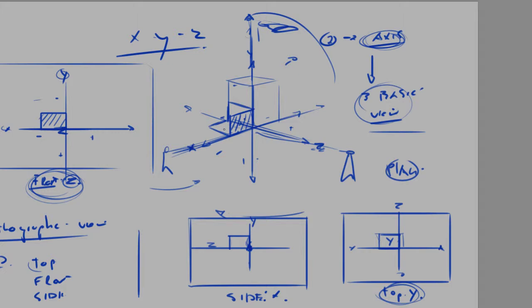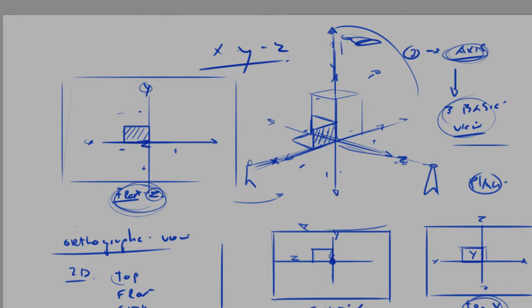So now let's say I want to take this y plane, looking down, and I want to extend. Let's extend on the front plane. So I'm going to take this front plane and just duplicate this over. We're going to find center on the Z plane. So this is looking from the front. This is essentially what I did. Now I'm going to find center on the Y axis. There's that, and then I'm going to cross over and duplicate into the positive X direction. So duplicate into positive X, there was the center, come through and actually come up and hit that, and I've duplicated into that direction.